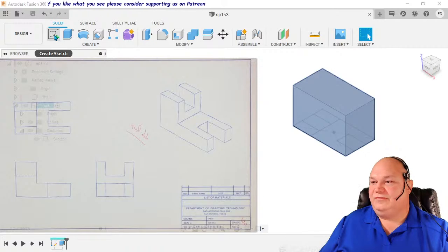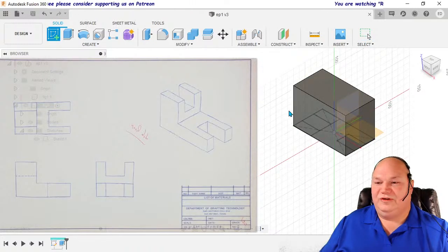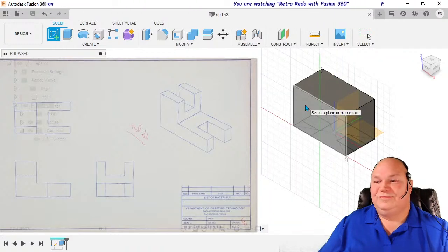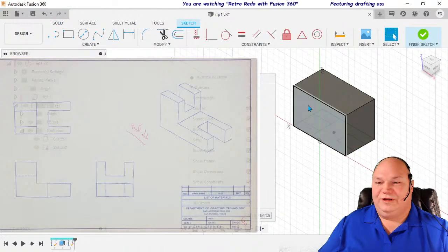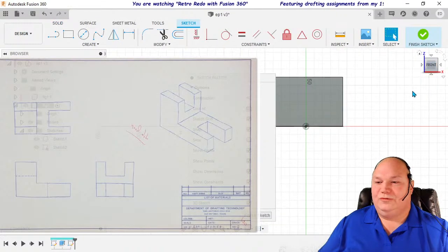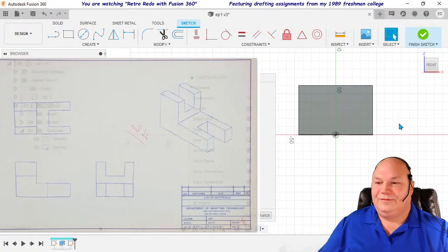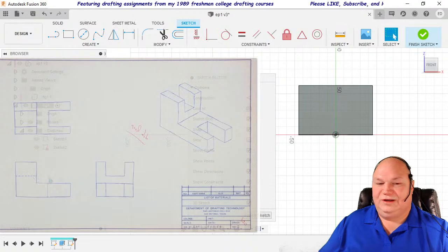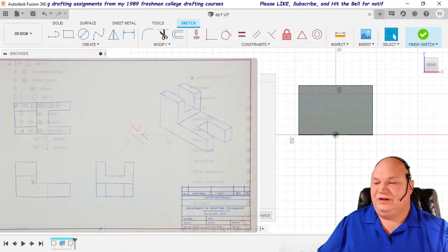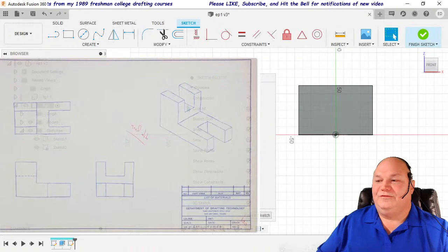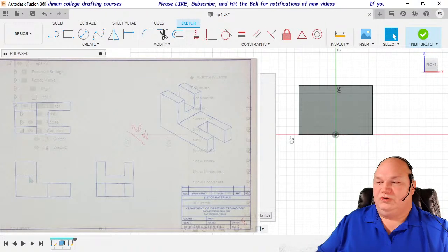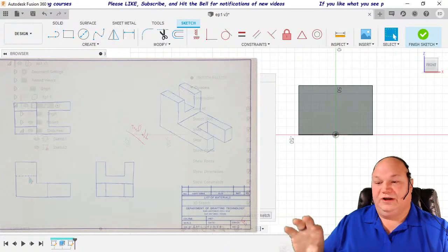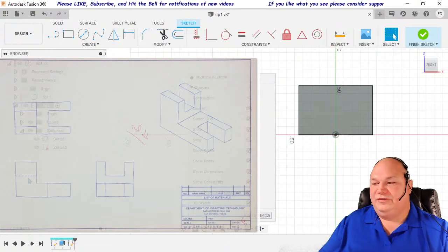So let's go ahead and create the side view. We're going to create another sketch, but this time, instead of putting it on one of the flat planes of the origin, we're sticking the sketch right on the side of the object. So plop, we're right on the object. We'll look at it straight on. Now we're going to draw almost this view. It shows hidden lines because this is the diagram of this object, and we're going to draw it with solid lines so those are different profiles, because we're going to do different things with the different profiles.